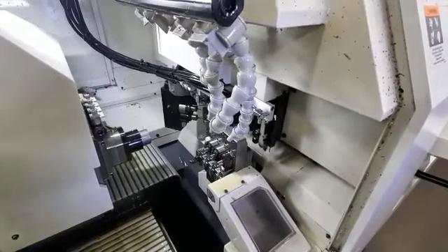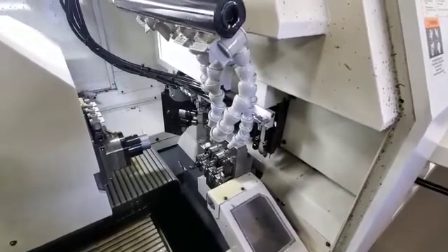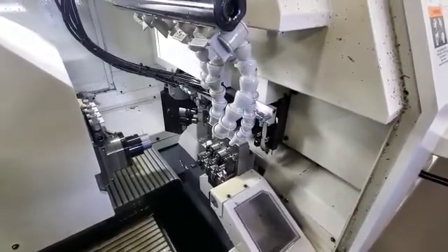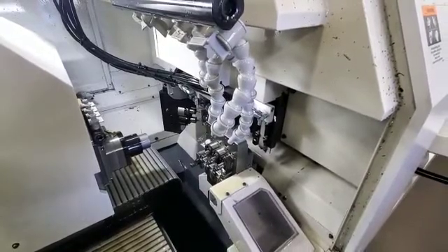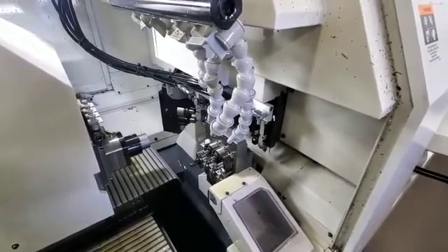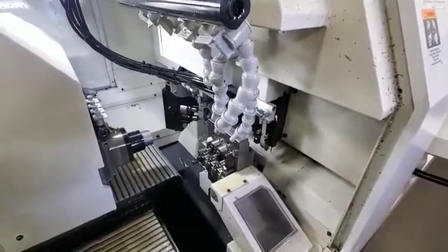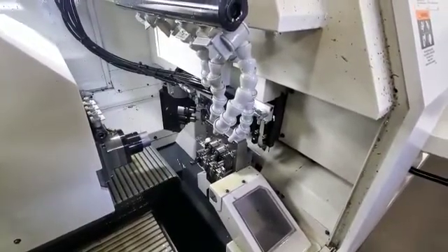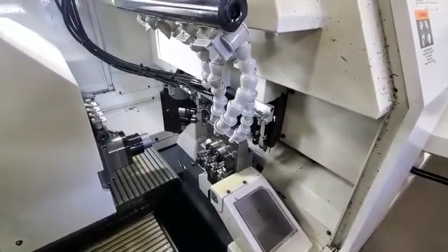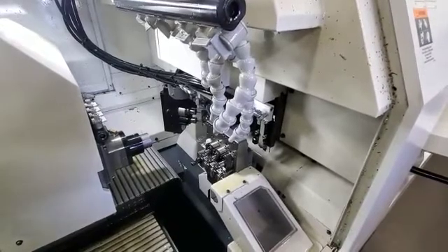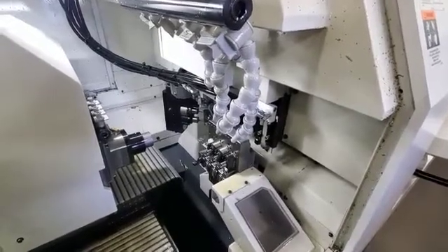It's simple and integrated into your main program, so there's no worrying about switching programs or anything like that. It just starts running production for you right after we hit cycle start here, and it will change that 575 macro back to a 0 automatically for you, and you're good to go.